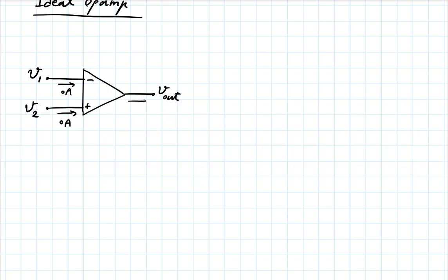The output current is what? It can be anything, right? Because remember, the output current comes from this internal thing that we modeled with a voltage-controlled voltage source as an ideal voltage source, which can provide any current. Of course, in a real op-amp, there are limits. But in an ideal op-amp the output resistance is 0, so it's a short circuit there, there is no voltage drop internally regardless of what current you're pulling, and so there's no limit on the current. And the current can be either way.